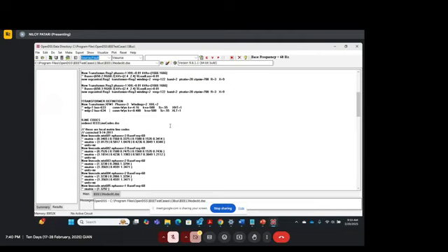So when I say primary distribution feeder and secondary distribution feeder, I'm not talking about the primary and secondary of a transformer. I'm talking about voltage levels. Even when you are distributing power from the substation end, we power engineers distribute power at a higher voltage. It can be 4.16 kV, it can be a bit more.